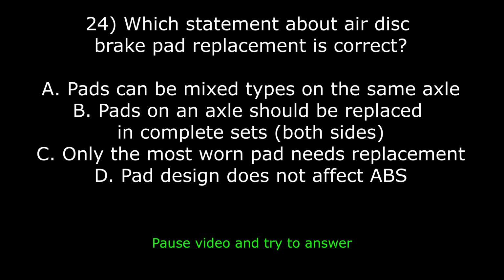25. Which statement about air disc brake pad replacement is correct? A. Pads can be mixed types on the same axle. B. Pads on an axle should be replaced in complete sets, both sides. C. Only the most worn pad needs replacement. D. Pad design does not affect ABS.